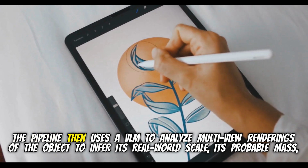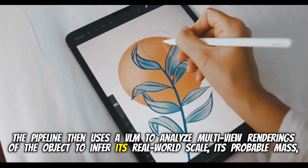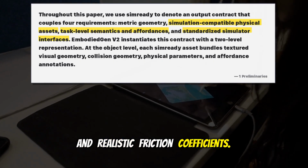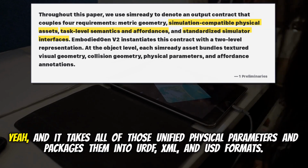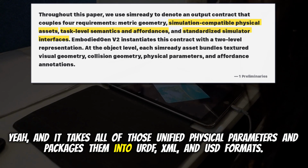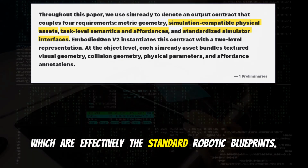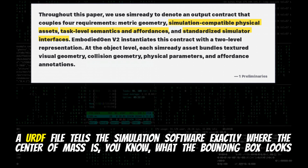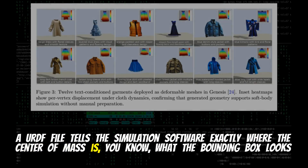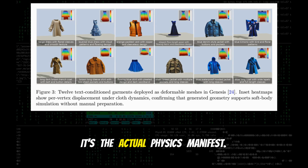The pipeline then uses a VLM to analyze multi-view renderings of the object to infer its real-world scale, its probable mass, and realistic friction coefficients. Yeah, it infers the friction. And it takes all of those unified physical parameters and packages them into URDF, XML, and USD formats. Which are effectively the standard robotic blueprints. A URDF file tells the simulation software exactly where the center of mass is, what the bounding box looks like, how the object should react to gravity. It's the actual physics manifest.